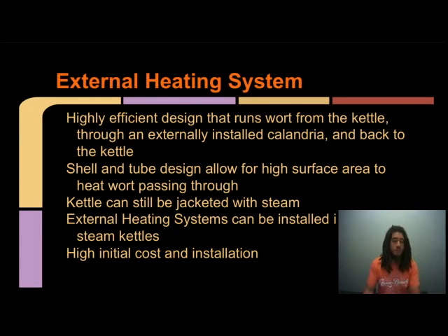All right, there are also external heating systems, which are essentially the same sort of technology as internal ones, but they're outside of the tank. It's a highly efficient design that runs wort from the kettle through an externally installed calandria and back to the kettle. Also called a shell and tube, it is a design that allows for high surface area to heat wort that's passing through it. The kettle, like in the internal, can also still be jacketed with steam.